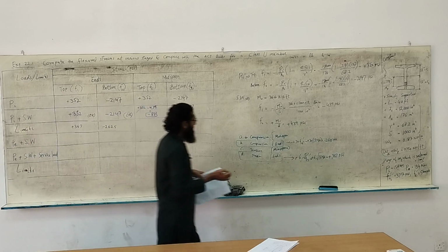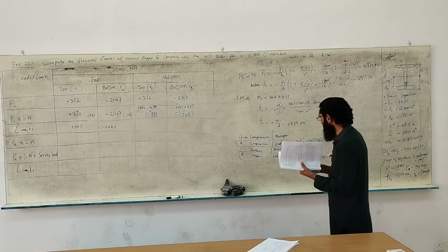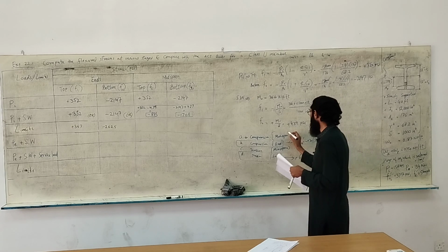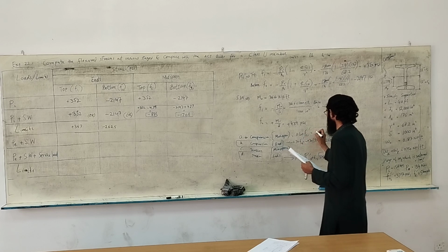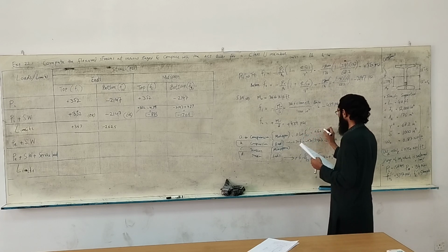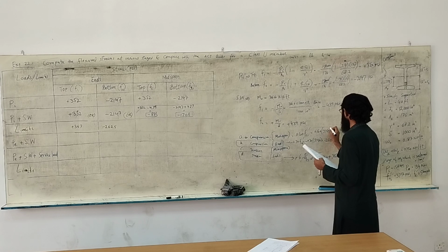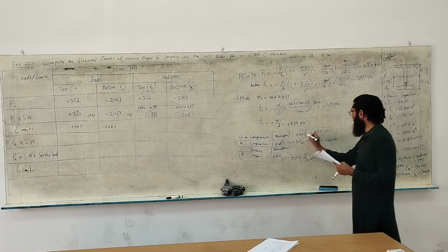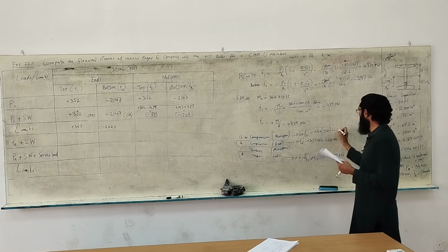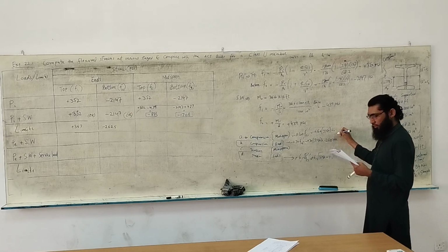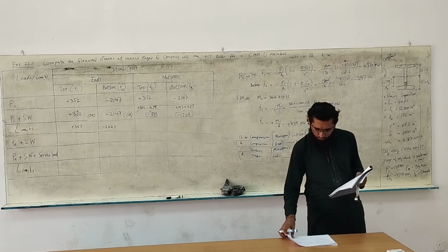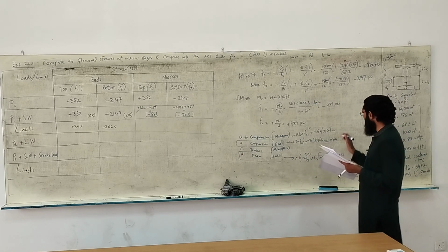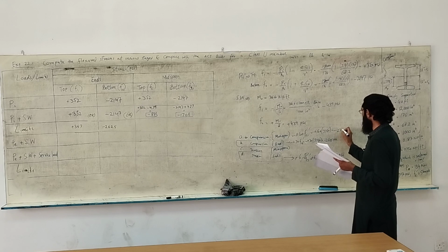What is next? At the midspan, compression at the midspan, the limit is 0.60 f'ci prime. So what is the answer for this? Maybe again we can put a negative sign over here. What's the value? Sorry? 2250 with a negative sign to tell that it's compressive.